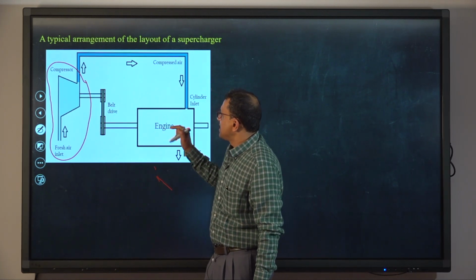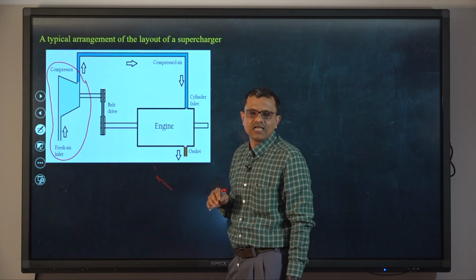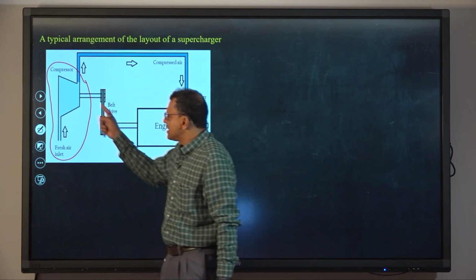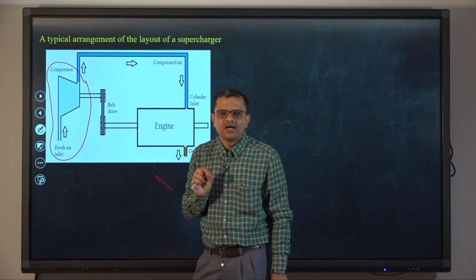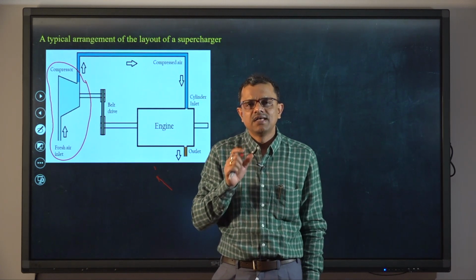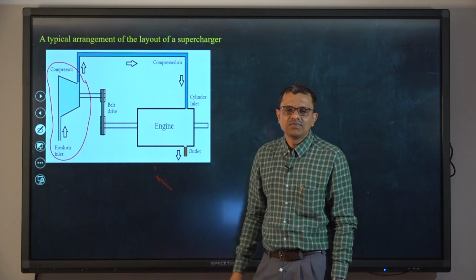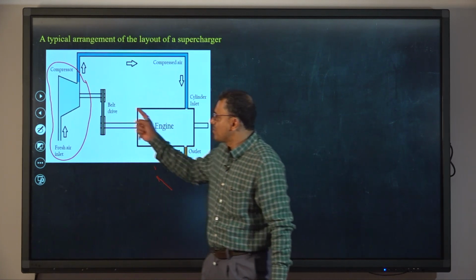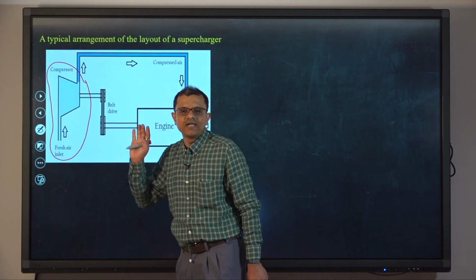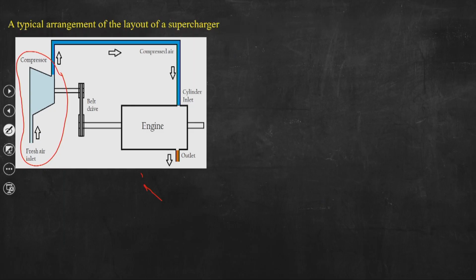Now, this compressed air is fed into the engine cylinder essentially to increase the mass of air, or air consumption rate. So, let us now consider this particular unit, and briefly recapitulate our basic understanding of thermodynamics to have a mathematical expression of the total pressure rise, or the amount of power that you need to supply to the compressor for its operation. So, if we take out this particular element, we can say that, okay.